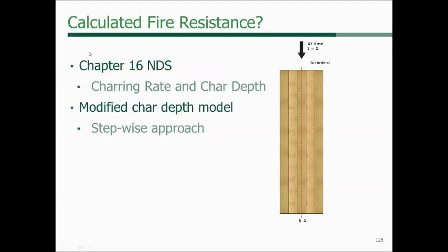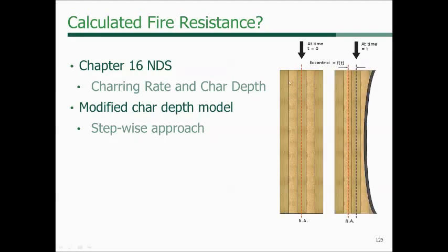We know that if we're looking at cross-laminated timber, say a wall panel, we have cross-laminated timber with 2x members or some type of nominal member vertically, so the grain of the wood is going up and down. Then the next layer, 90 degrees to that, has the grain in and out of the page, so you would see end grain here. And so they alternate, thus the name cross-laminated timber.